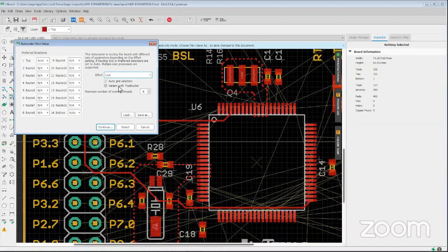So I think, what was it, Ed? Like 3 years ago, 2.5, we introduced the top router. A little longer than that, so maybe 4 years for the top router. So the top router is basically a more intelligent algorithm. It actually uses sophisticated maths, namely Voronoi diagrams, to break apart the design and determine these optimum paths where routing should happen. It makes a mini sketch. It passes that along to the old autorouter, which then uses it as a basis to form the routes to do the autorouting.